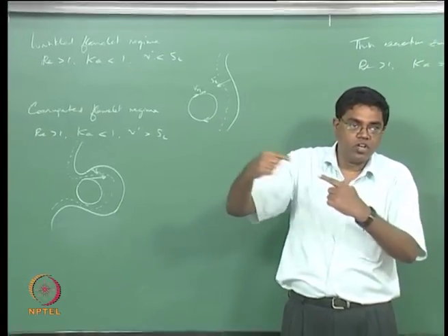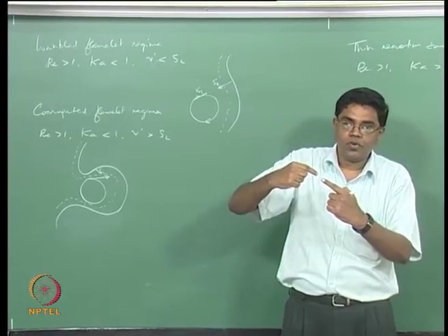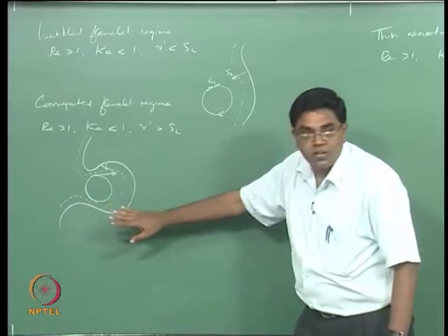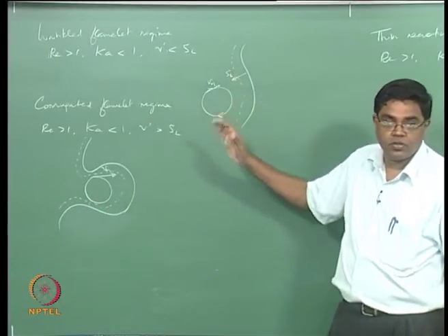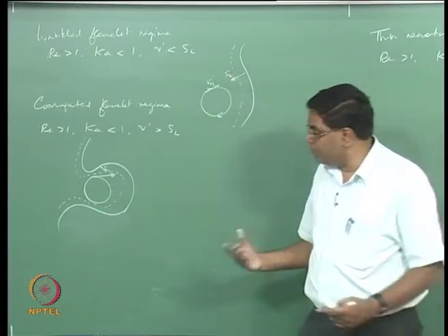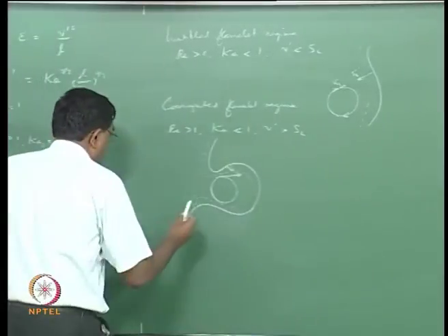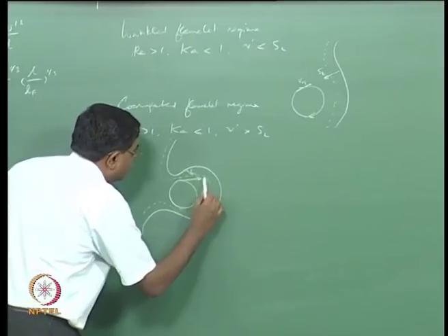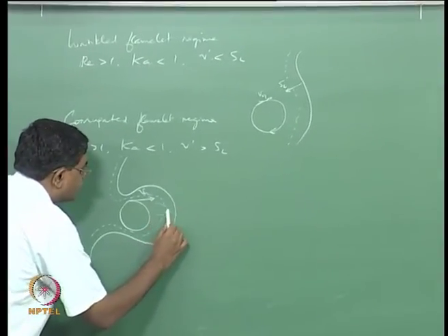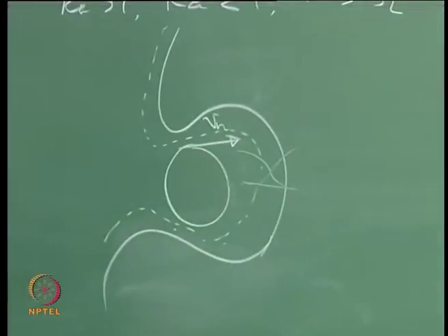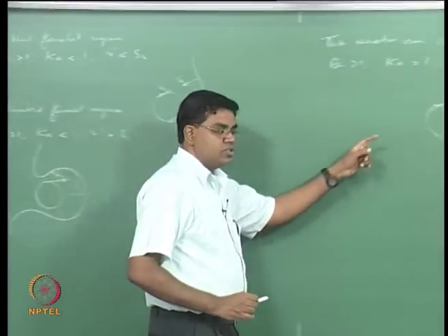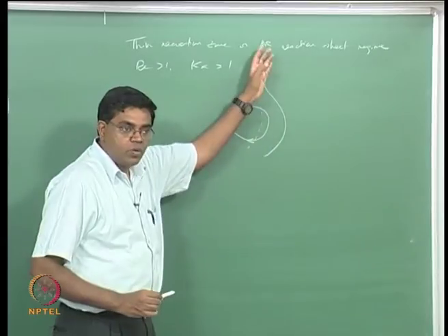Locally the flame is trying to match the flow, right, or it's shaping itself to match the flow, and that happens everywhere still, right. So you could hold on to that. That means locally if you look at these gradients, you can draw exactly the same pictures that you drew, that is, the concentrations are falling down, the temperature is growing up and all that stuff. That structure is there, right, but here that structure is breached, okay, except only for the reaction zone.